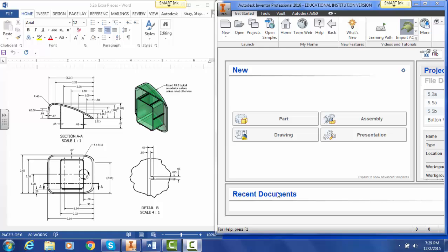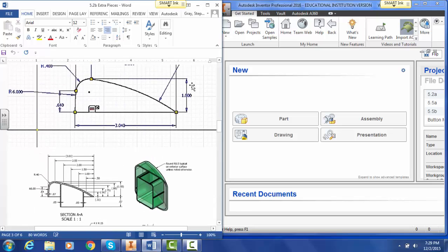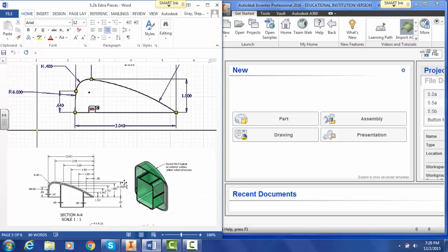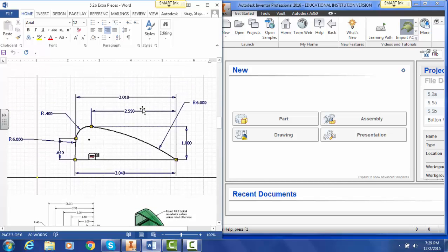Okay, we're going to create this windshield right here, and to do that I'm going to draw the profile of this windshield like this, and then I'm going to extrude that, and then I'll start making this inside piece. Now the video that I uploaded on Echo, he had you use a lot of construction lines, but I'm actually going to sketch the outline of this profile as best I can, and then I'm going to use my dimensioning tools to add dimensions to it, and it will automatically take the correct shape and size.